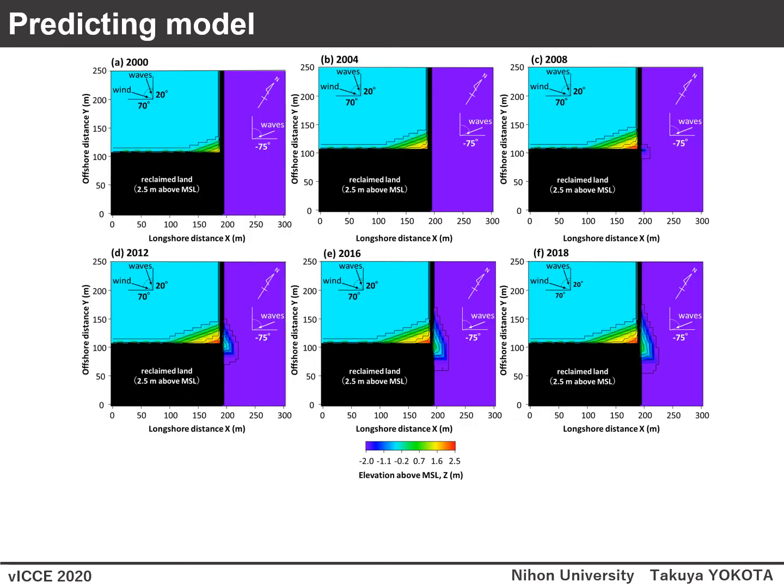The West Beach has gradually formed since 2000, and windblown sand was transported over the port breakwater over time and deposited inside the port after 2008. At the corner of the port breakwater and the seawall, windblown sand has been deposited and the ground elevation has increased. This is in good agreement with the conditions measured in the field observation.